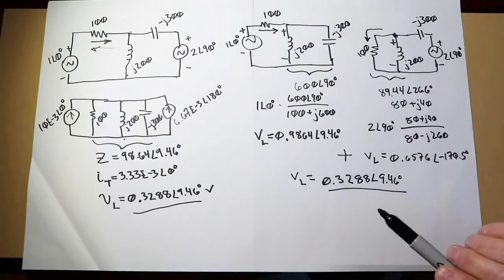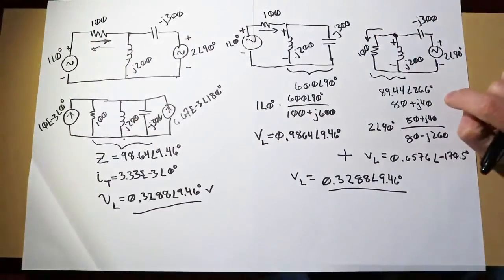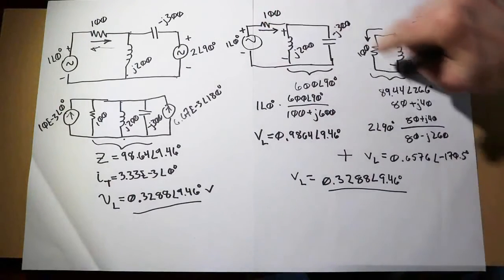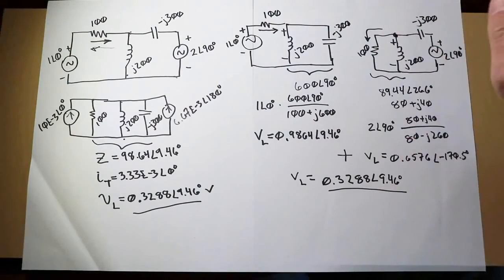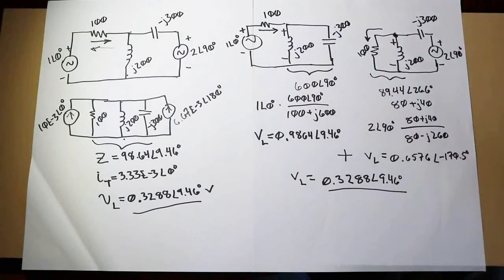Here's a good way to remember that. In this particular case, these two currents are going in opposite directions. Now, if you were to just calculate the power, let's say by using I squared R here and I squared R here, well, the sign, whether it's positive or negative, disappears, right? When you square it, a negative current turns into a positive squared value. So it wouldn't really make any difference on your calculation, right? So that tells you immediately, yeah, that can't work.